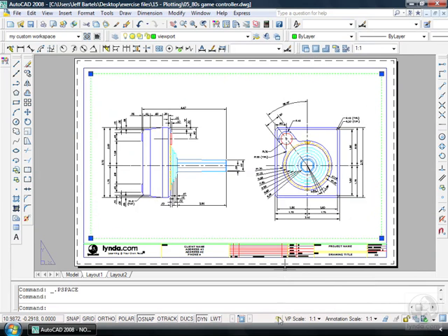All right, now that I've set the scale of my viewport, I'm going to protect myself. I'm going to come down and click my lock button. This will prevent the viewport scale from changing. If I do wish to change this viewport in the future, all I have to do is highlight it, come down here and unlock it, and then I can change the scale. Let me hit my escape key to clear the grips. And let's address one more thing.